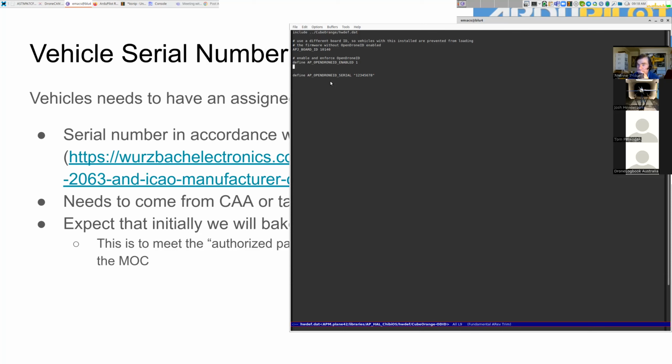If there's multiple flight controllers, would you need to differentiate between each flight controller, or could you say it's a vehicle ID? Okay. So if you've got multiple redundant flight controllers in your vehicle, then I'd say use CAN, because that way the CAN bus is common, hopefully between them, and they can all get that arming status, etc. Otherwise, it should be that this ID is just a vehicle ID, which is on the transmitter module and is common. In fact, the flight controller doesn't even need to know this ID, because the transmitter module would be broadcasting it directly.